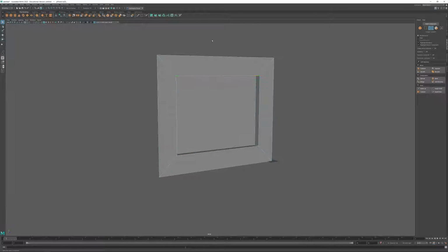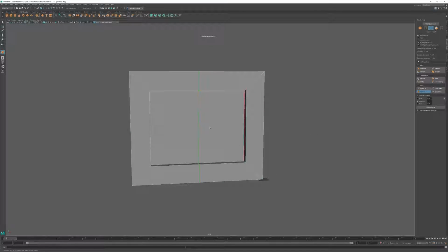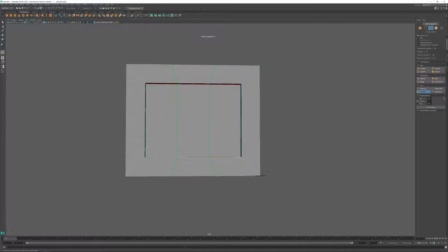These are the ones that run left and right. I'm just going to marquee through the model to do this. I'm going to go to the connect section. And since I want to create 3 equally spaced windows here, with segments selected, I can middle mouse click and drag to the right to create 2 new edges. When pleased, I will hit enter to accept.